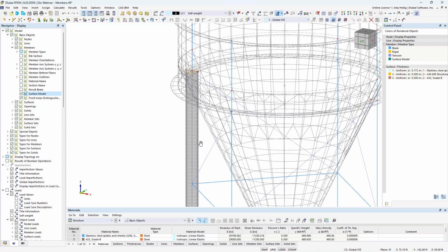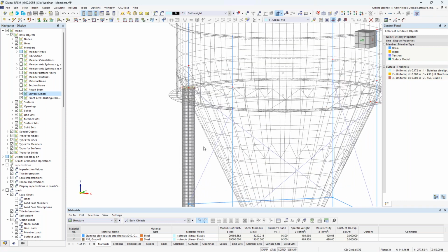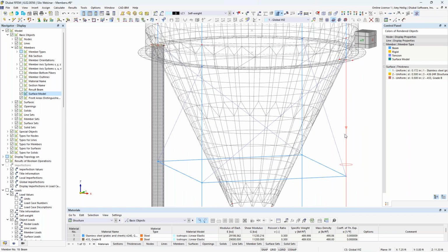What's happening here is that the program has created the 1D member element, as we see with the rest of the columns, that we can move forward with the AISC design and the steel design add-on a little bit later on, but it's also creating a secondary element here for the surface. And this surface will allow me to perform a more in-depth stress analysis and design, for example.